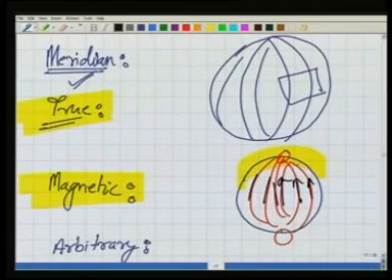Now as you can see, getting a magnetic needle is very easy, it's not tough. So we can say establishing a magnetic meridian is also easy. You just take a magnetic needle, suspend it, and the direction it is making is the meridian. So we can define it as a plane in which our magnetic needle has oriented itself. Again, for a small area, we can consider these magnetic meridians also to be parallel to each other, while for the entire earth they converge again at the poles, the magnetic poles.